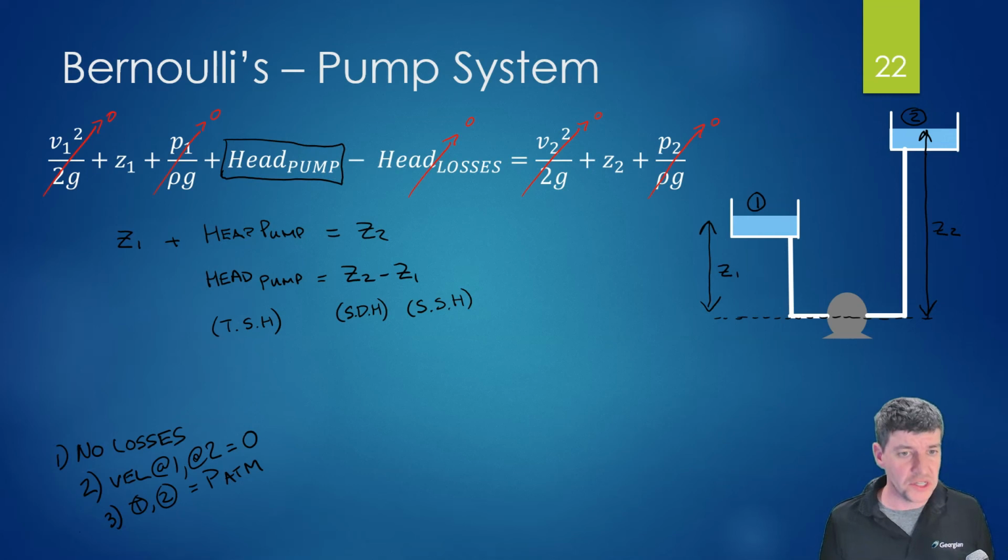And if we get into the situation where we have a suction head or a suction lift, really with the idea that as we go up, it's a positive, or if it's below the pump, it's a negative, then Bernoulli's should be able to give us the right equation, whether it's a positive Z value or a negative Z value relative to that pump's location. Okay, so Bernoulli's can be a good tool if we start to use it for this type of analysis.